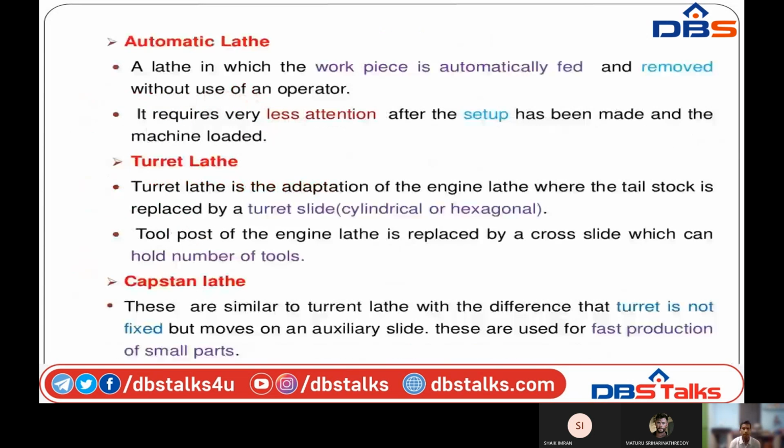Automatic lathe is one in which the workpiece is fed automatically. Here we are not giving manual feeding. The workpiece is placed at the jaws of the chuck, that means the headstock position. The tool is placed at the tool post. When we set an automatic feed, the removal of metal or excess material from the workpiece is done by the automatic feed. By giving automatic feed, the lead screw moves along the axis of direction facing the workpiece.